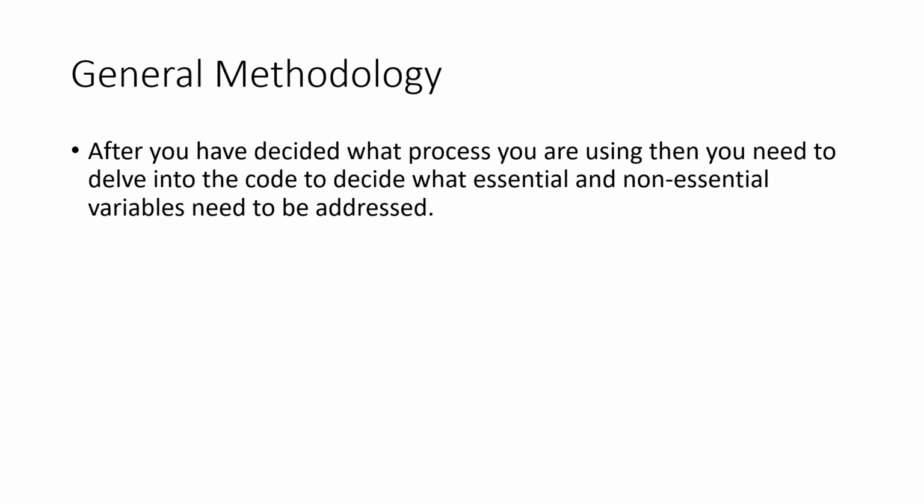You're going to provide these essential variables and instructions to your welder in the form of the pWPS, the preliminary welding procedure specification, the work instruction for the weld test coupon. And you're probably going to want to throw on some non-essential variables that need to be addressed also. You're going to try and provide them some instructions, such as cleaning, filler metal sizes, that type of stuff.